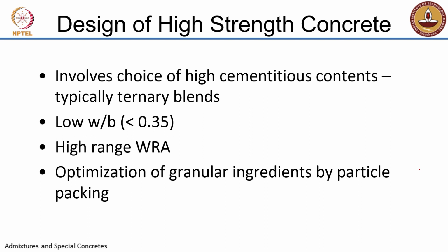Now, for obvious reasons, we'll have to use cementitious blends that are high in overall cementitious content, right? We want to maximize the usage of cementitious material to get the advantage not just from the hydration reactions but also from the packing that comes about because of the use of such fine materials, right?